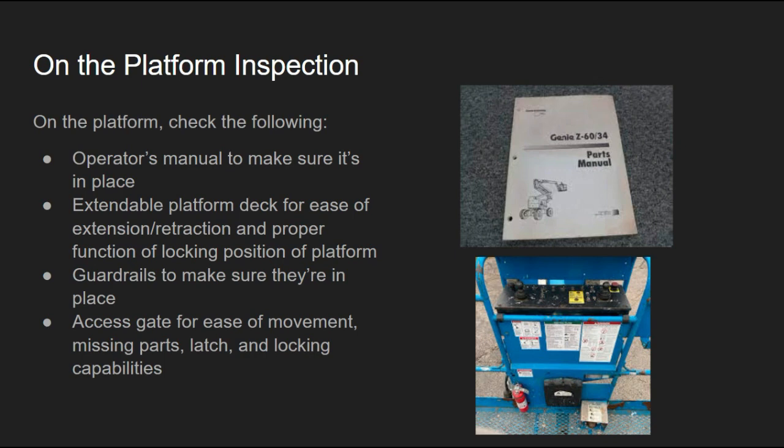Operator's manual, to make sure it's in place. Extendable platform deck, for ease of extension, retraction, and proper function of the locking position of the platform. Check the guardrails to make sure they're in place. Check the access gate for ease of movement. Check for missing parts, and that latch and locking capabilities are working.